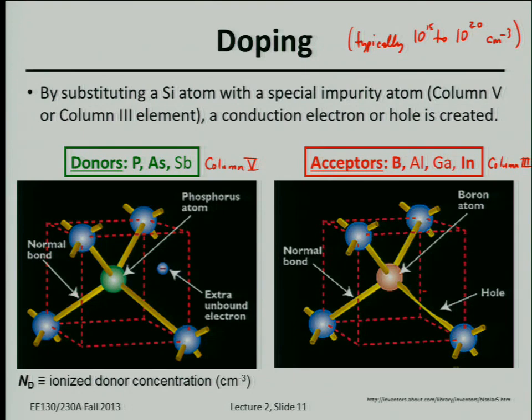Yes, the extra electron conducts current, right? But I'm just saying in certain regions of a semiconductor device, the carriers are free to move around. So they can diffuse away because of a concentration gradient, or there can be an electric field that pulls them away. So it's very common in a semiconductor, whenever you have a junction, when you have very steep changes in dopant concentration, that the electrons will leave the vicinity of the donors, and the holes will leave the vicinity of the acceptors. And in those regions, that's where you have some net charge density in the semiconductor, and that's where you have voltage dropped, because there's electric field and so on.